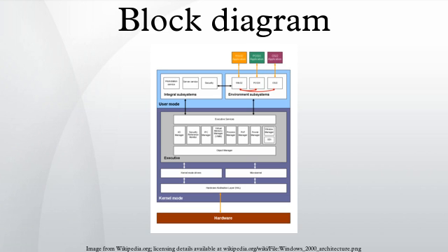Directed lines are used to connect input variables to function inputs, function outputs to output variables, and function outputs to inputs of other functions. These blocks portray mathematical or logical operations that occur in time sequence. They do not represent the physical entities, such as processors or relays, that perform those operations. Each block is therefore a black box. The rules require the logical sequence to go from left to right and top to bottom.